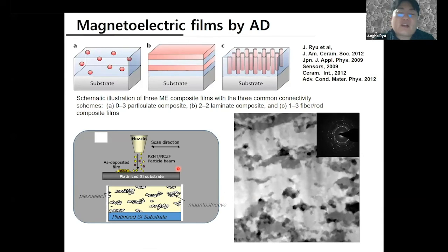And we were trying to make some kind of composite. Actually, my main background is magnetic material and piezoelectric material, mixing together and making composite. So we synthesized the PZT-based material and the ferrite materials mixture. We sprayed this kind of particulate composite, which is possible, and also we made a lot of layer structures, as you see in the acoustic emission sensor slide.